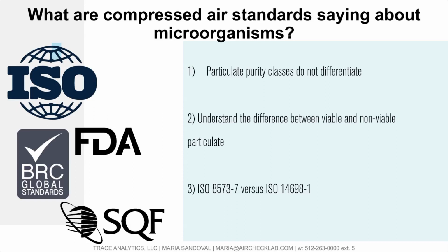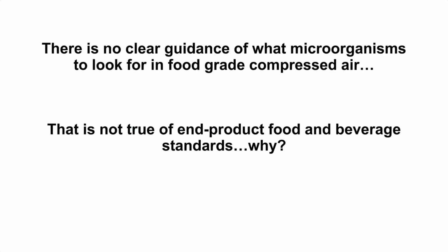So when you say you want to be compliant to ISO 14698, you would lean on ISO 8573-7 for those test methods. But since there's no clear guidance on what microorganisms to look for in food grade compressed air, we're left in this kind of ether of possibilities.